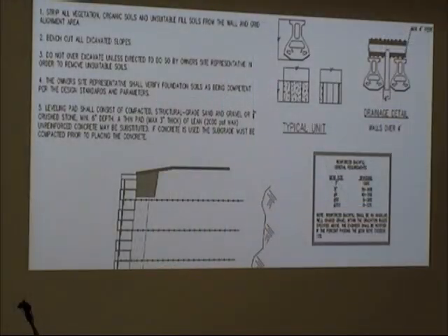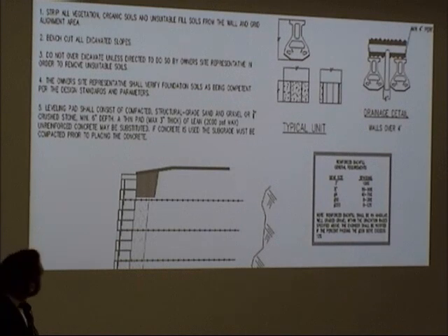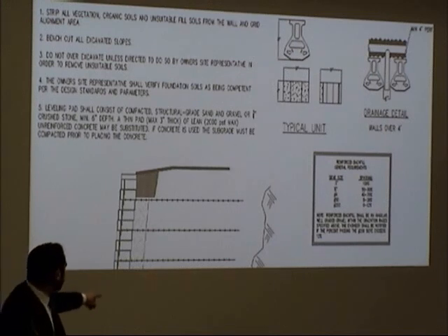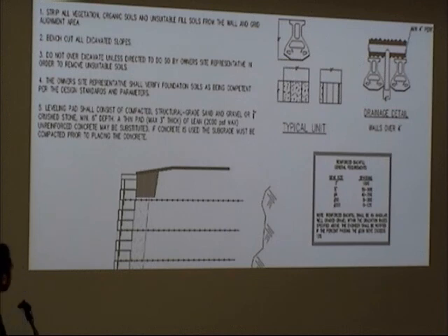But another thing we were asked to design was a retaining wall. For this retaining wall, we decided to go with a geogrid wall. And this is a plan that we came up with for our proposed geogrid wall. We have our block detail, drainage detail, some information about the material that we specified, and some general notes pertaining to material as well. It's a shame you can't see it, but at the bottom of this we have a drainage detail, and this is our wall face, our geogrid layer, and some impervious fill.